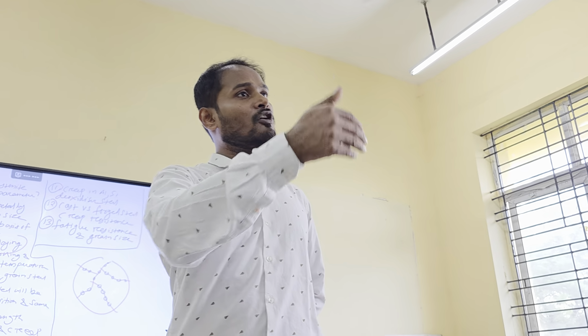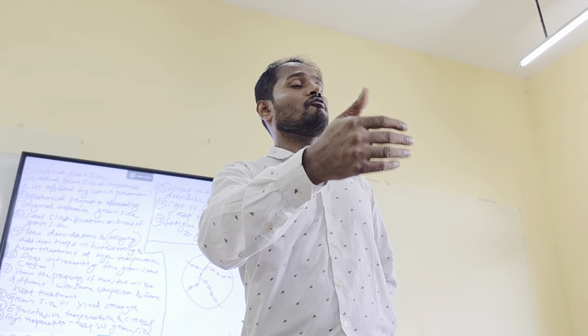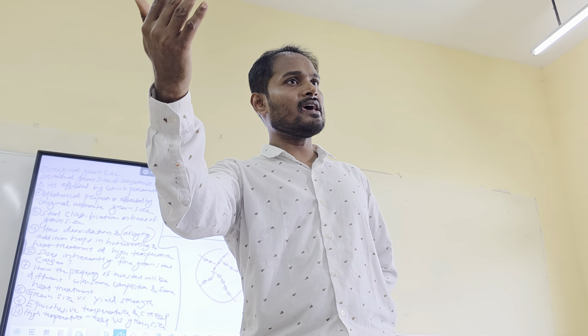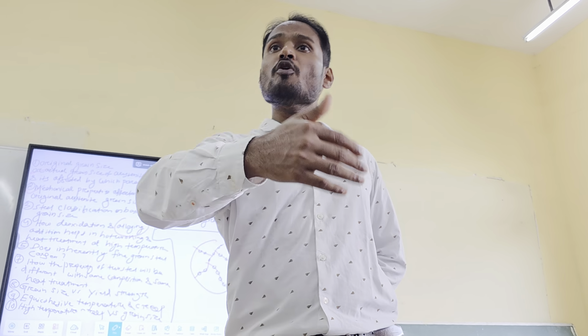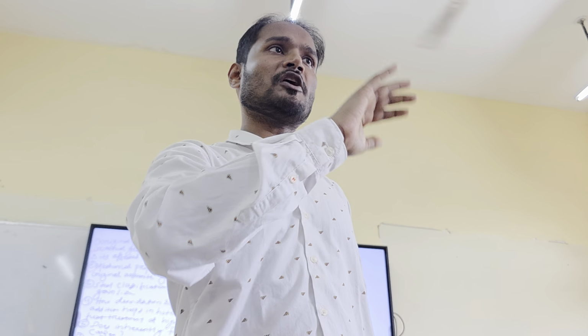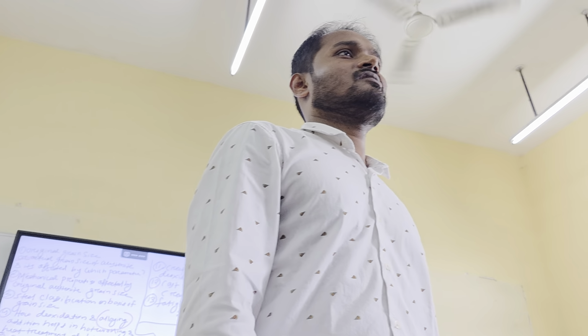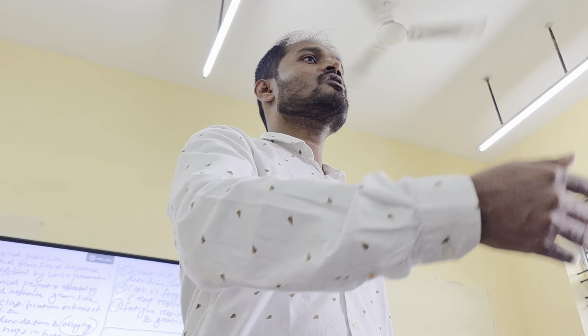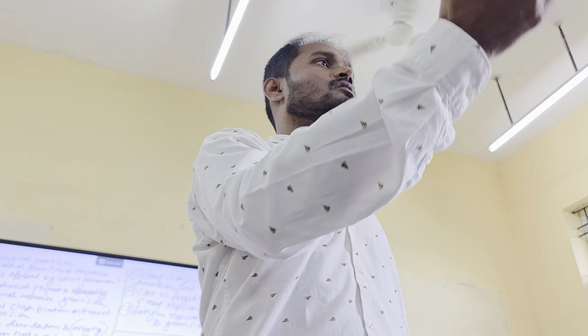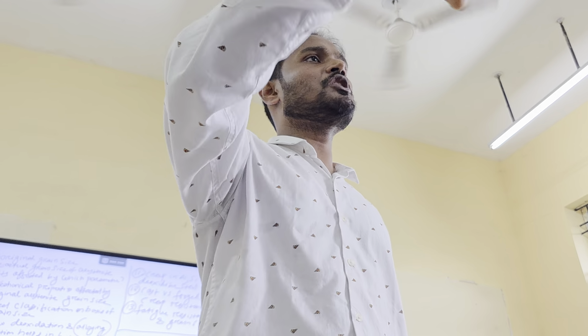Vacuum, yeah, he knows that, vacuum degassing. But basically to remove oxygen, we do deoxidation, not vacuum. Vacuum is basically used to remove nitrogen gas and hydrogen gas. But to remove dissolved oxygen, we do deoxidation. That is not a vacuum process basically. We add some alloying elements, ferroalloys, like ferrosilicon, ferromanganese, ferrotitanium, something we need to add.